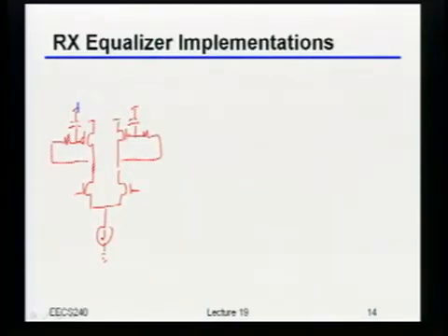Okay, so by the way, maybe MOS caps is a good idea too, but actually, remember, it's a PMOS transistor. So this gate point here is always referenced to the supply. It's always referenced to the source. So we want to make sure that VGS is constant. Better tie this cap up to VDD. Okay? But other than that, indeed, this is exactly the sort of active inductor load that we just talked about. It's just that now I'm not spending any extra bias current to do it.